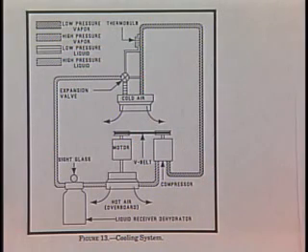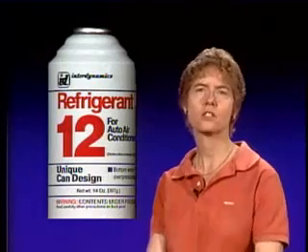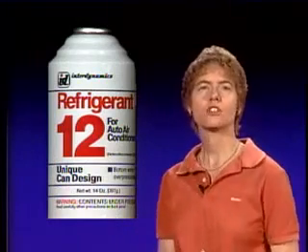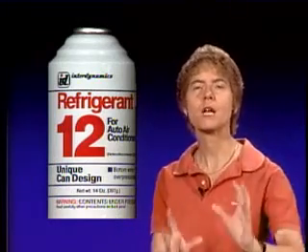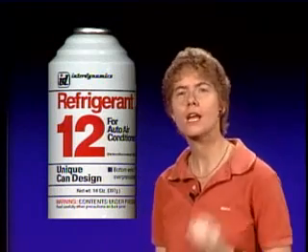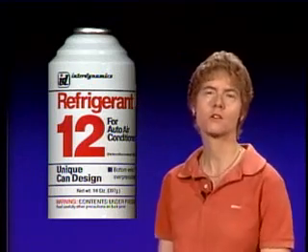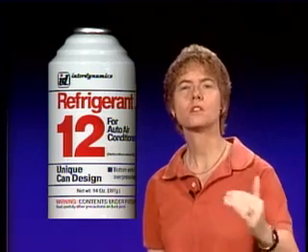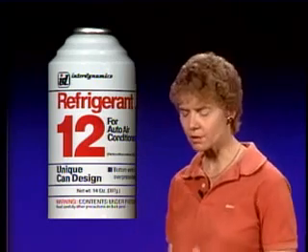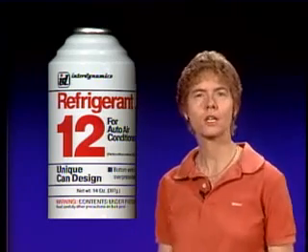So when you're purging the Freon air conditioning system, you need to release that charge very slowly. Release the charge at a very slow rate, and the purpose of doing it at a slow rate is you do not want to lose the refrigerant oil. You want to keep that refrigerant oil in there.